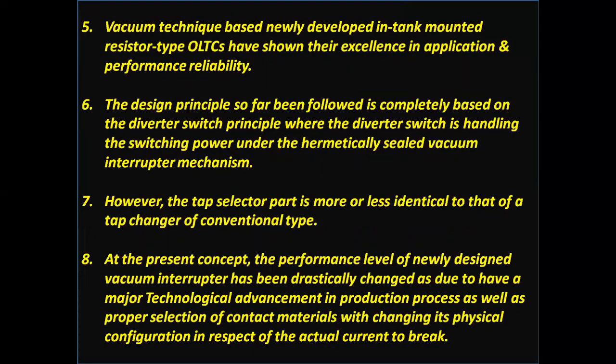Vacuum technique based, newly developed in-tank mounted resistor type OLTCs have shown their excellence in application and performance reliability. Resistor type OLTCs are mostly used in India and Asian countries as well as most of the European countries.